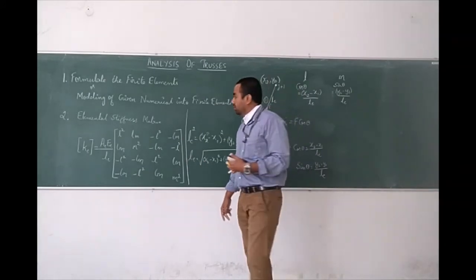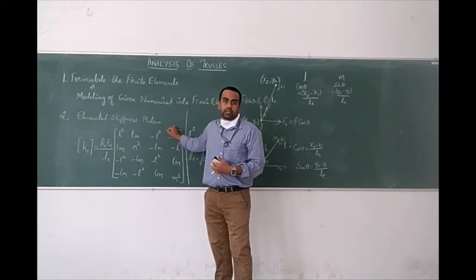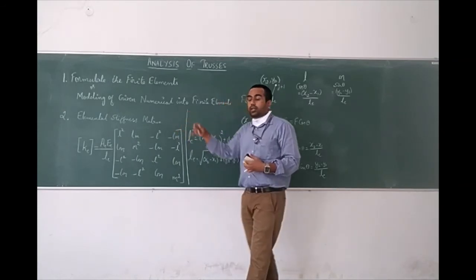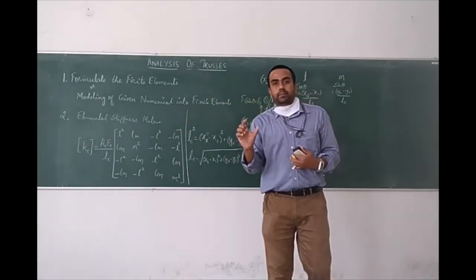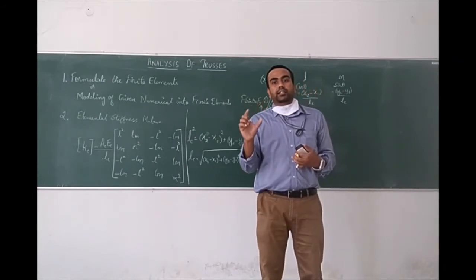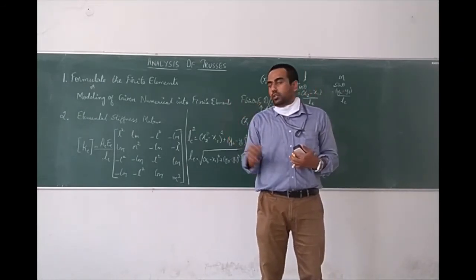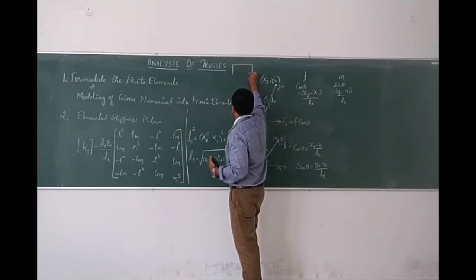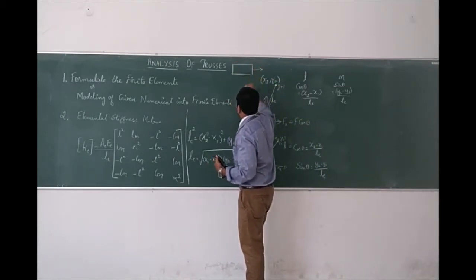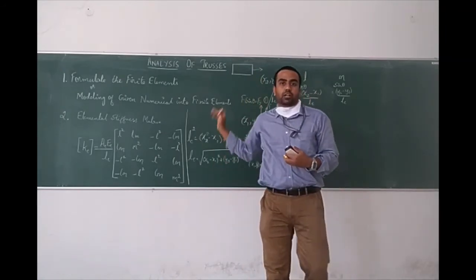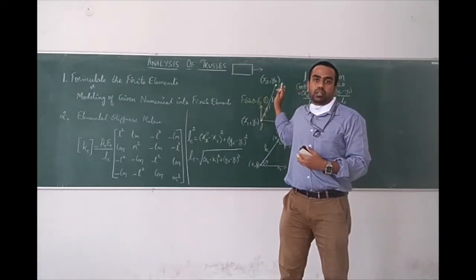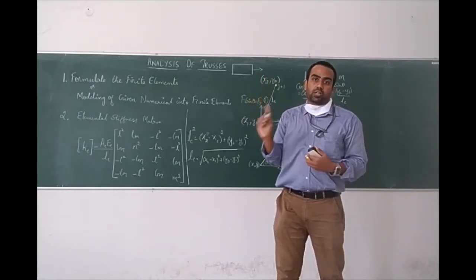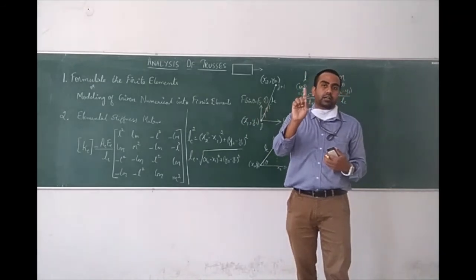As I told you, we can denote the global degrees of freedom on this stiffness matrix. So when we took bars, bars had only displacement in one direction. So here this is a bar and there was a force acting. The displacement used to be only along x direction. There is no displacement along the y direction. So degrees of freedom was only one for one particular node.